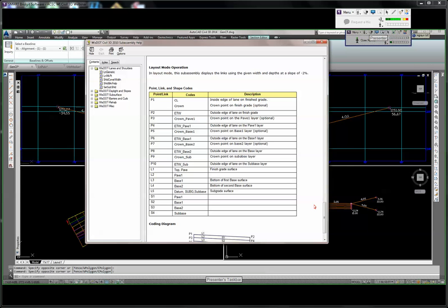A little bit later, I'm going to add in a code, and you'll see that I'm very, very particular about how I type it in, and it's because I looked it up in the help file, and I know the spelling, the capitalization, where the underscores are, where the spacing is, that kind of thing is all critical to this. If you spell something wrong or get something wrong about the code, you are creating a new one rather than just using one that's already baked into the subassembly.